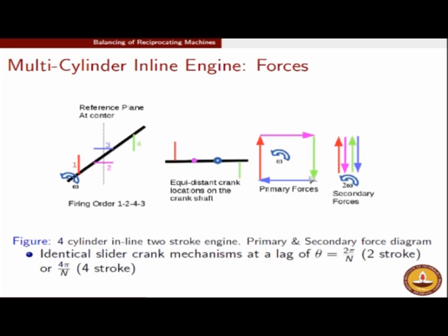But even then, for the sake of completion, if we wish to draw all the forces, as I said, the way to determine these shaking forces is to first consider the rotating unbalances and then take the x component of it. So at this stage we are not worried about taking the x component. We will just find the total rotating unbalance due to this group of forces.